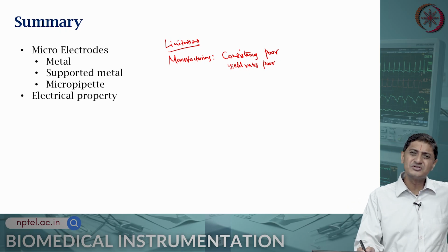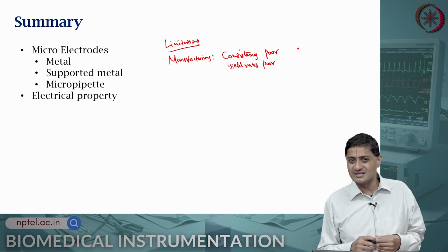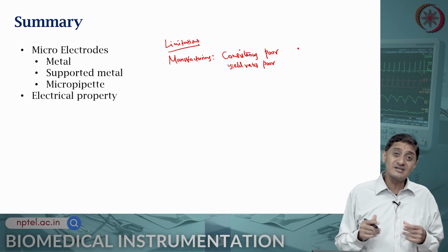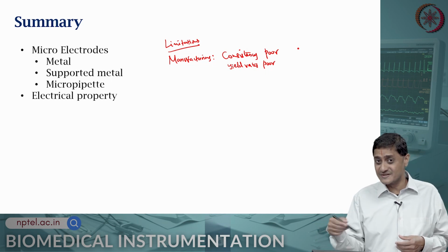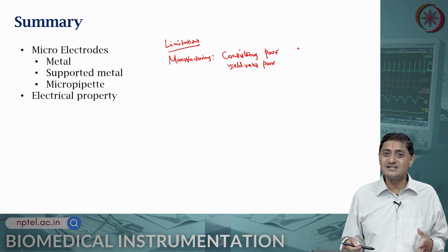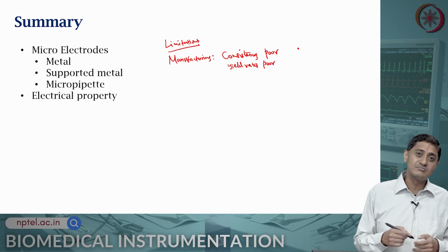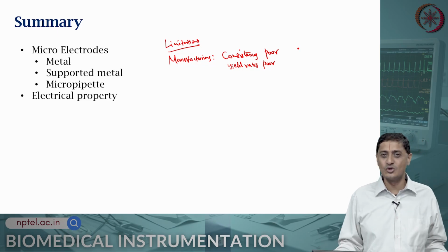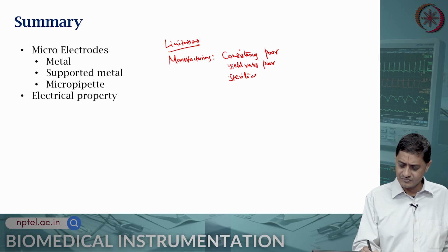And when you need to sterilize, because sometimes you use low melting point alloys, if you sterilize in an autoclave, it is possible that the geometry will change. You might be using it in studies that require sterilization across repeated use, and if you sterilize in between and the electrode changes, then you have essentially lost the electrode. Because some of the fabrication techniques, by design, use low melting point metals, sterilization is problematic. These are some of the challenges.